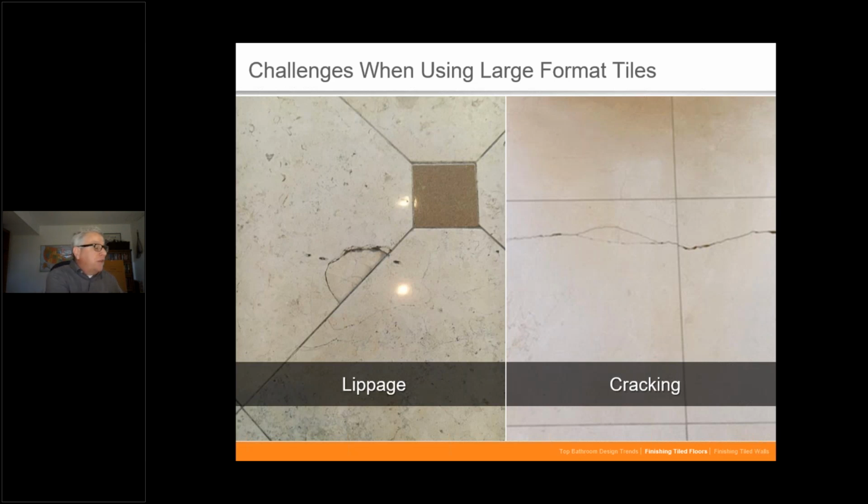That's why I thought it'd be a good idea for you to have either this book or this type of ANSI book that I've got here, because this will actually give you the specifications on how flat the floor needs to be. Also, what comes into play is your bond coat, say your thin set mortar that you're going to use to actually put the tile in. So those things are all coming into play.